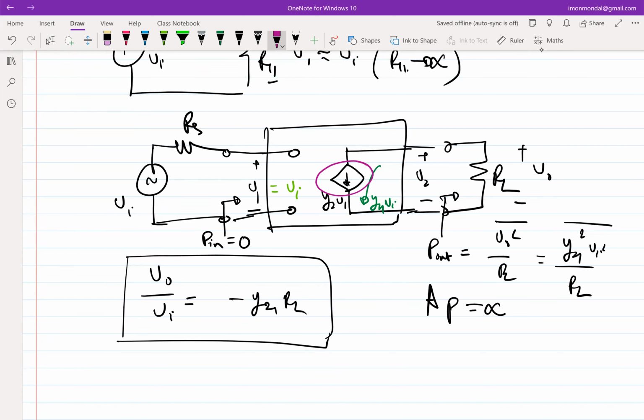So if you take the total power, the quiescent power plus input power, that will always be less than the total output power. But in this picture, we are not showing the quiescent power. Okay. Does that make sense? So in truest sense, power conservation still holds. It is not as if you are getting more output power than input power, but you can get more power at a certain frequency than the power you are extracting from the source at that frequency.